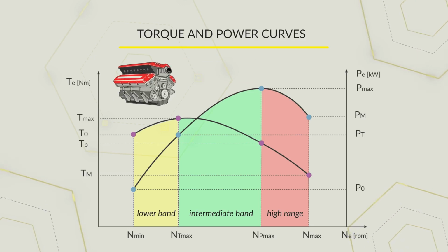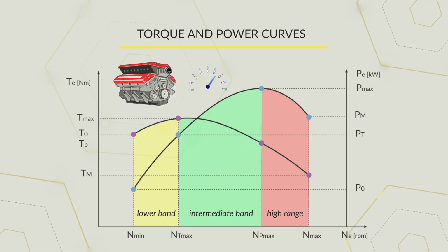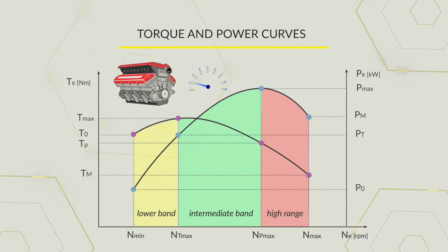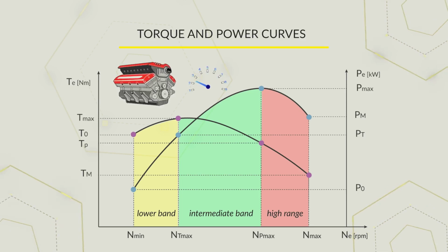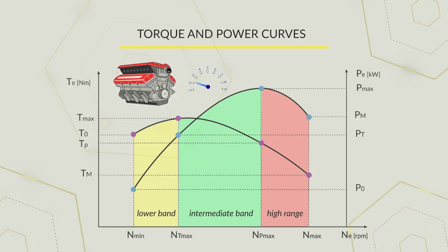When the engine works within the high range, if for any reason the friction forces were to increase, the engine RPMs would decrease, causing a decrease in the engine torque. But in any case, it would drop in the intermediate range without unstable conditions.